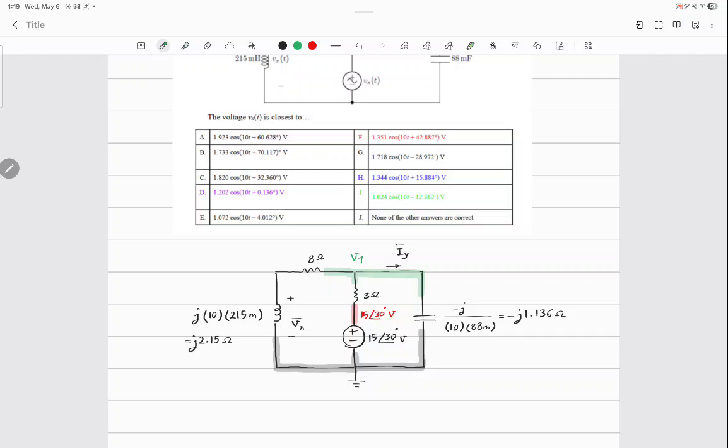Voltage division, okay? So this is the part that's trickier compared to the first two examples. Sometimes you have to break your problem into two problems to avoid getting into a system of equations. If I combine these two, I can do just one nodal analysis and get on with it. But since I cannot do a system of two equations and two unknowns, I better find V1 first and then do a voltage division, okay? Is there any other way that you can think of? I don't see.